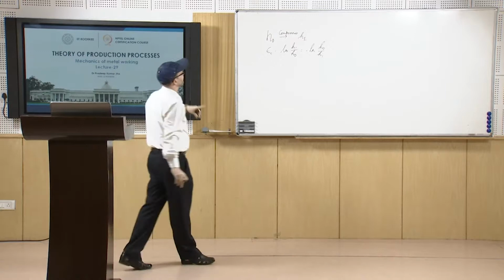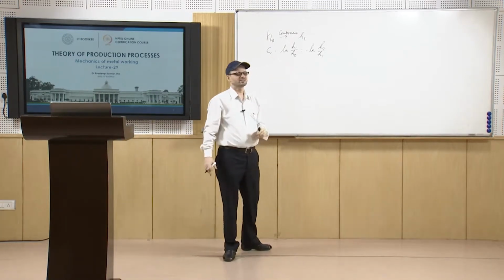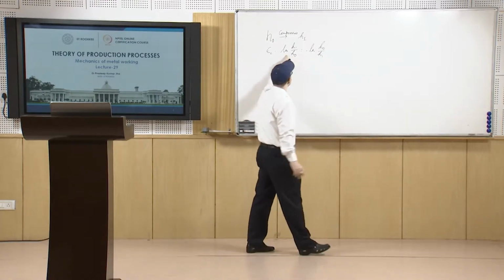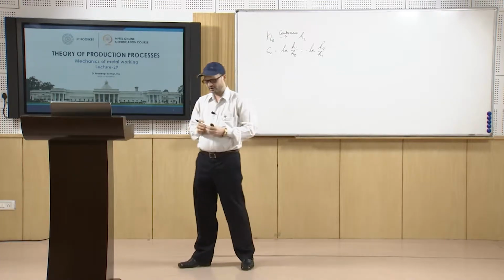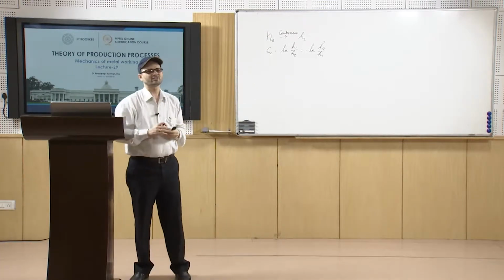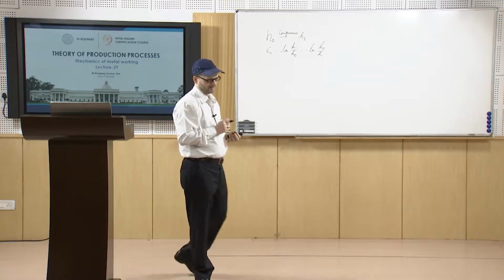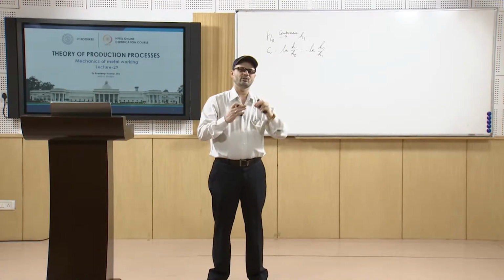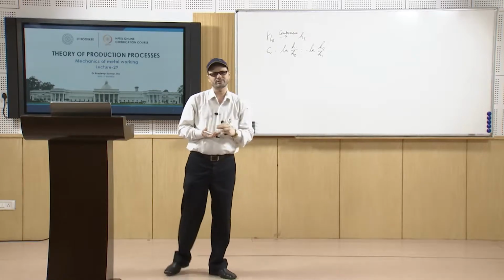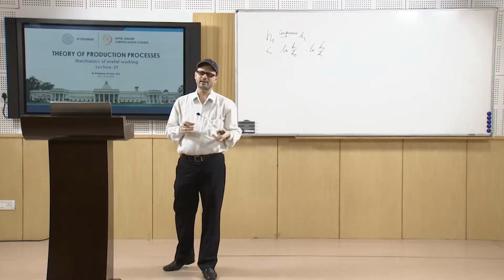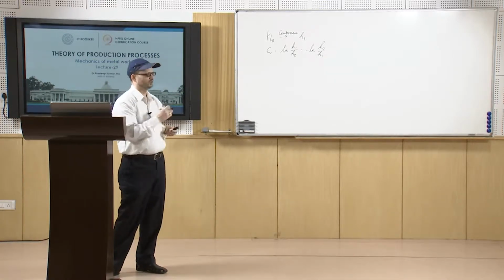In normal practice, because it becomes minus of ln, we will see that in the later part. In such cases we take it as a positive value, because in the case of compressive strains, or in plastic deformation, the height is always decreasing, so you would always have to take the negative value. Conventionally, we take it as positive. So, let us see how we do it.